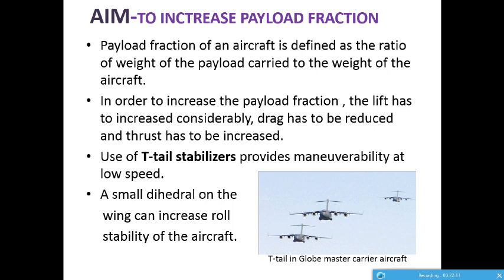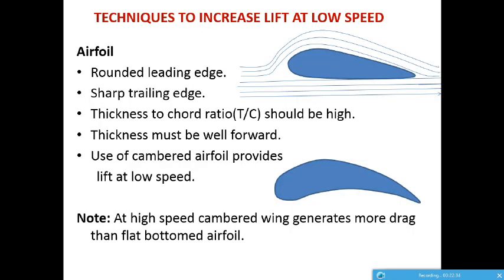But using T-tail stabilizers, you can keep the control surfaces away from the turbulent flow, so that maneuverability can be achieved at low speeds. Here are some of the techniques to increase lift at low speed, such as rounded leading edge, sharp trailing edge. Okay, let's move to the next slide.